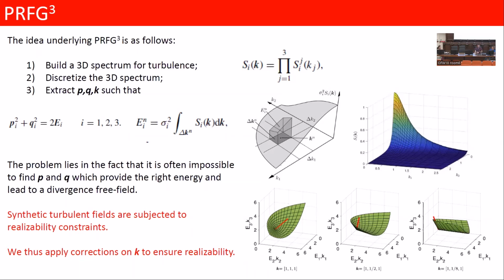So you need to start by having this big turbulence spectra in 3 dimensions, one spectrum for each velocity component. And we have, let's say, a very simple method, by multiplication, to generate this turbulence spectra starting from the 9 length scales. It's an assumption basically, but we can do that. So knowing the 9 length scales, you generate a 3D turbulence spectra, and what you do is just discretize your wavelength domain. At each frequency, basically, you assign a power for the 3 velocity components.